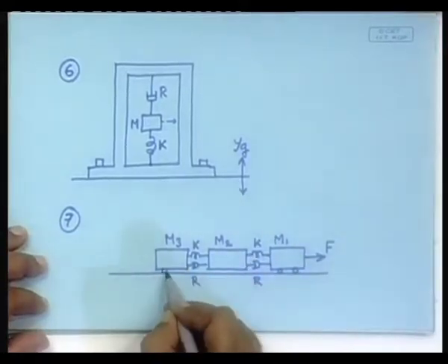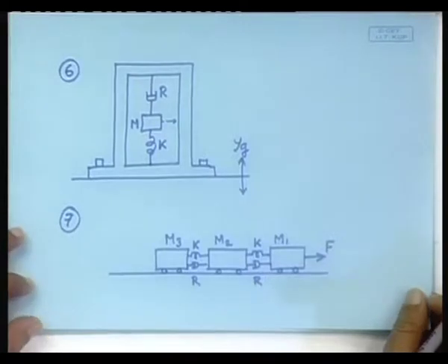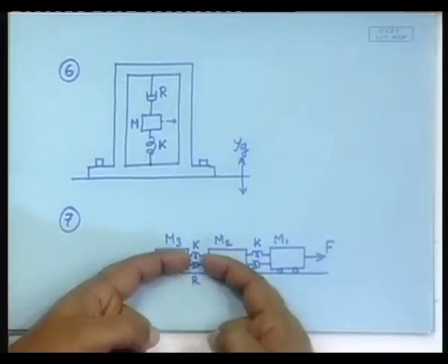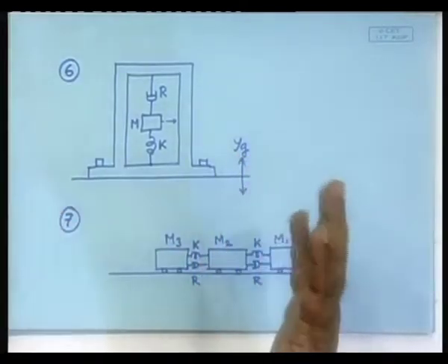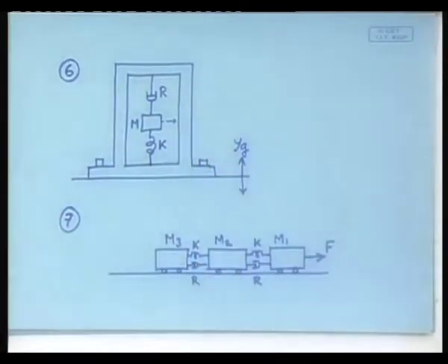They will all individually have their own degrees of freedom. In actual practice there is a limit to which these things can be compressed. In actual practice there are two hard plates which can collide with each other. So, compression is limited, but the tension is not limited, and this compression being limited is what? It is a non-holonomic constraint. So, if you have a non-holonomic constraint, then also the same set of differential equations have to be obtained. So, that is what you obtain, those differential equations.